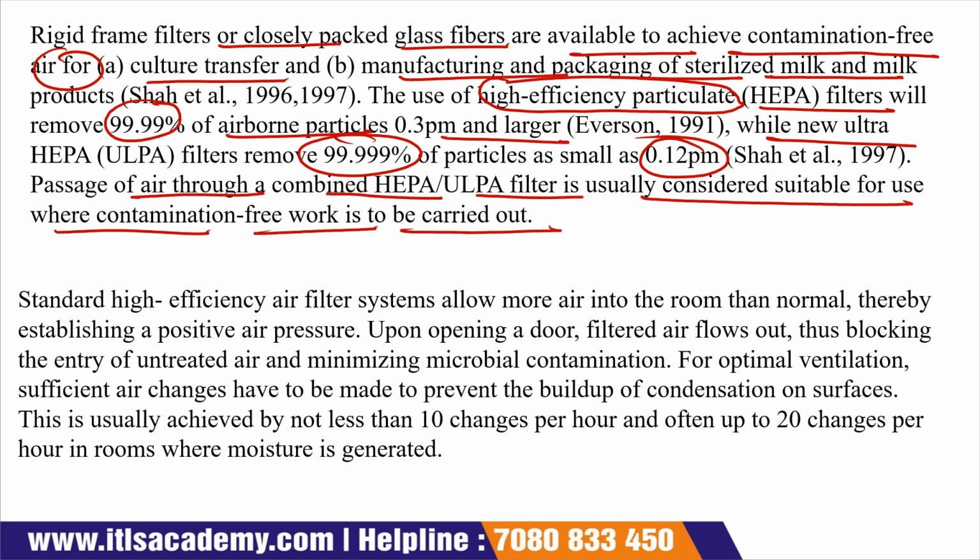Okay, so at that area where contamination-free work should be carried out, we use a HEPA or a ULPA filter. The HEPA filter will remove 99.99% of airborne particles, including microorganisms of 0.3 µm size, and the ULPA filter can remove 99.999% of particles, as small as 0.12 µm in size, of these microorganisms.